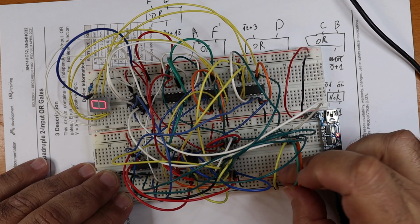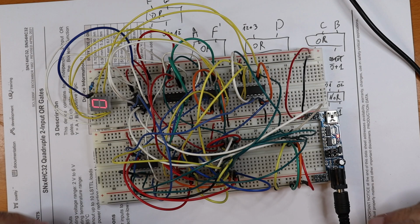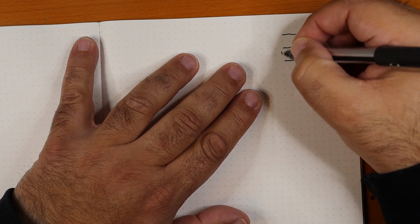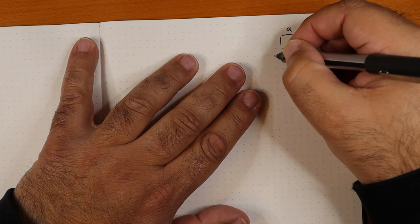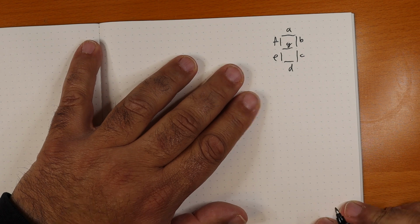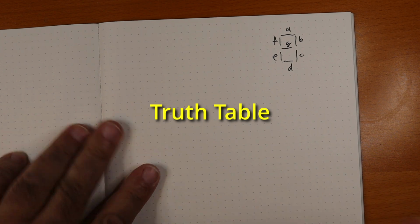So how do we go about designing such a circuit? The first step in designing a 7-segment decoder, or in fact any circuit, is deciding what the requirements are. A 7-segment display is composed of, well, 7 segments, and we're going to label them A, B, C, D, E, F, G, because that's the standard way to label them. Now we need to make something called a truth table, which means we have 4 inputs.